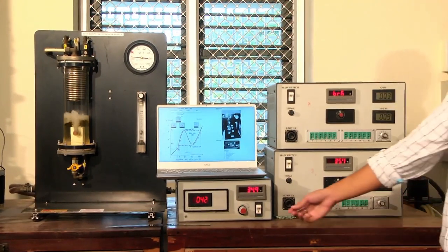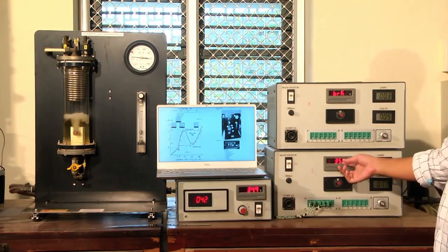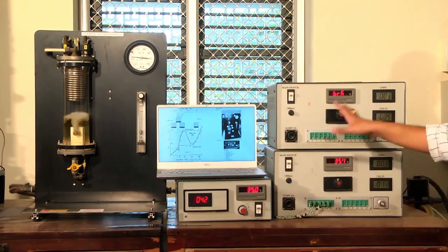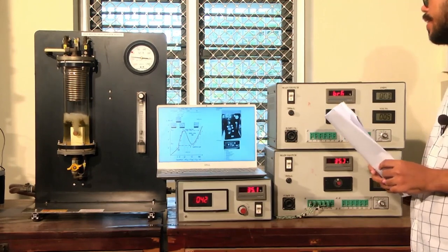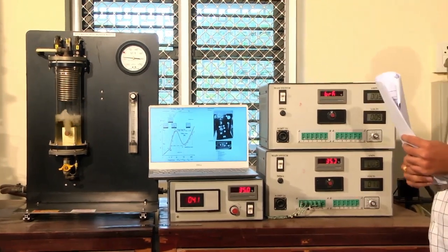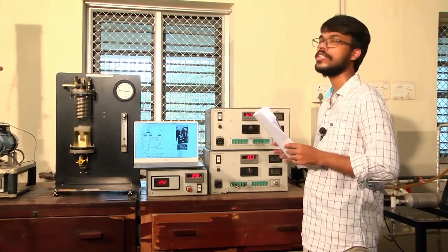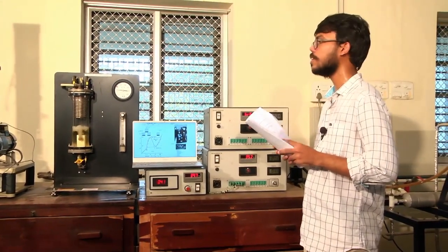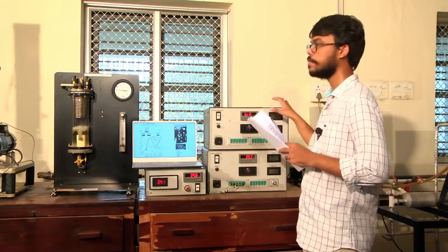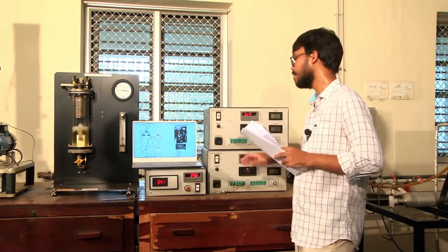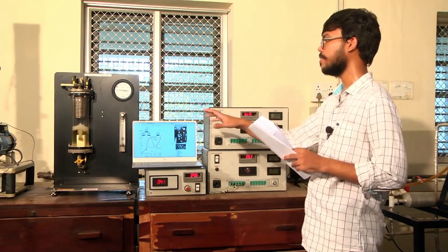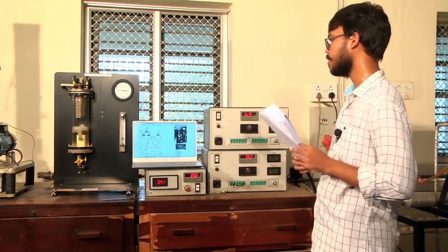As we increase the heat flux, the surface temperature increases, and this setup has been designed so that it could reach only up to 160 degrees, because beyond that temperature the critical heat flux is reached and the solid gets melted. So, in order to prevent thermal failure, there is a temperature controller here which stops the heater if the surface temperature reaches 160 degrees.